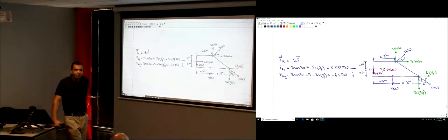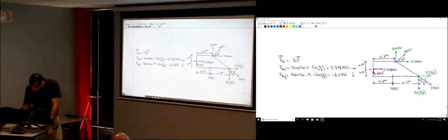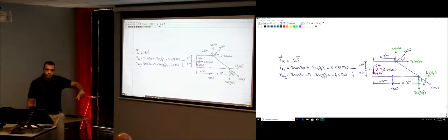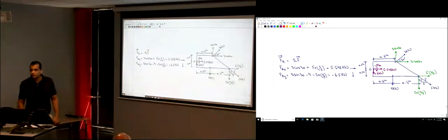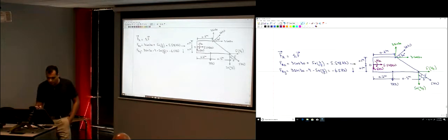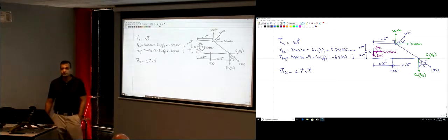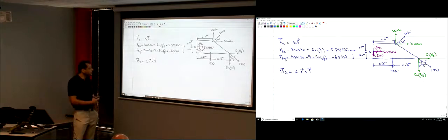Okay? How much is that moment? There is a moment here, MR, a resultant moment. What's MR? It's the moment of each of those forces about point O. I just have to sum this together. So MR is just the summation of R cross F, if you're going to do it in Cartesian vector notation. Or you can use scalar quantities.